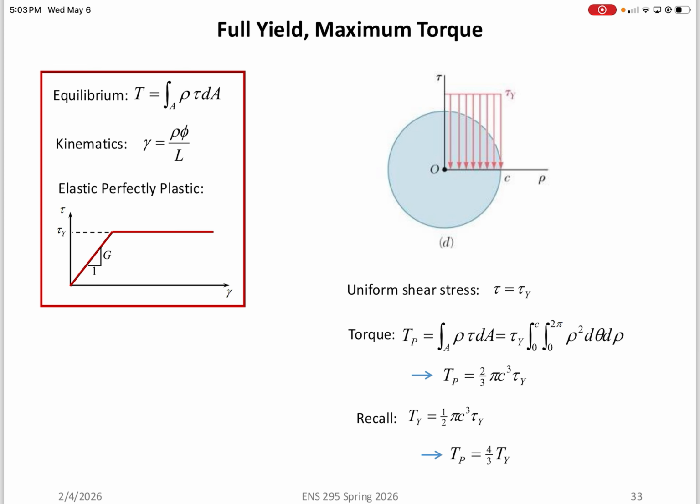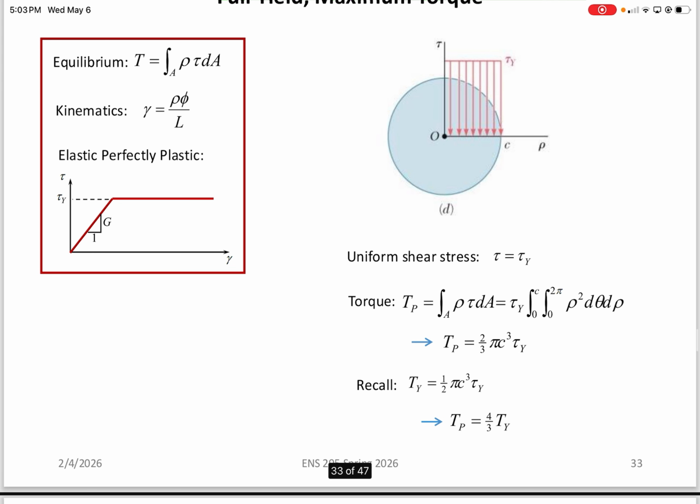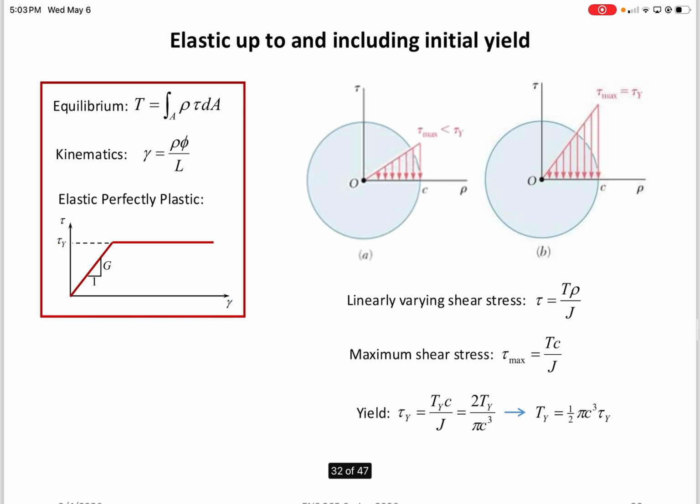So, for example, for a fully yielded cross-section, from the center of the rod to point C, we found that the torque assumed for full plasticity is roughly 4/3 times the torque calculated using a straight-up linear elastic stress distribution, increasing from 0 to the yield stress.